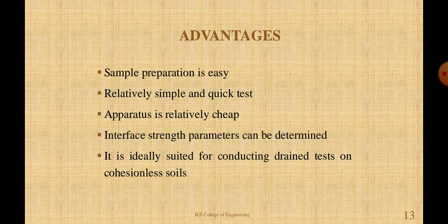The advantages of direct shear test. Sample preparation is easy. Relatively simple and quick test. Apparatus is relatively cheap. Different strength parameters can be determined. It is ideally suited for conducting drained test on cohesionless soil.